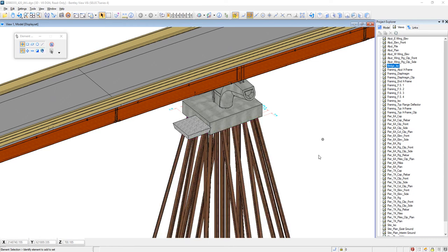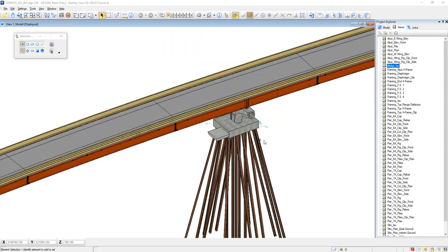So we'll go ahead and select out of here and unselect those elements. If we do a right selection or create a right box, again by holding down the mouse key, you can see that the boundary of that box is not dashed. We'll go ahead and do approximately the same box, and nothing was selected. By going to the right, the elements have to be fully within that box. So because the piles are sticking up below and above that box, it's not going to give us that selection.